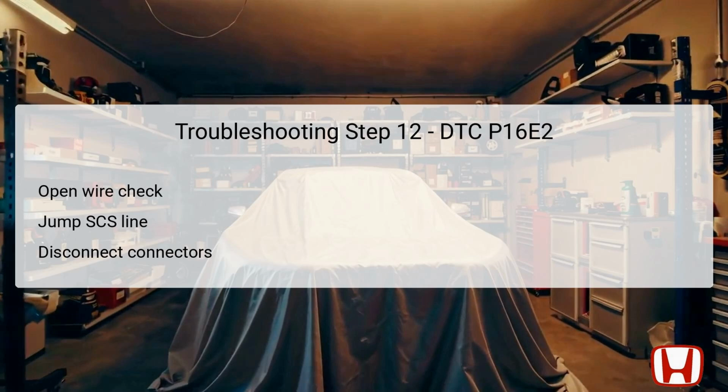If the resistance measures 1.0 ohms or below, the LIN wire is operational.